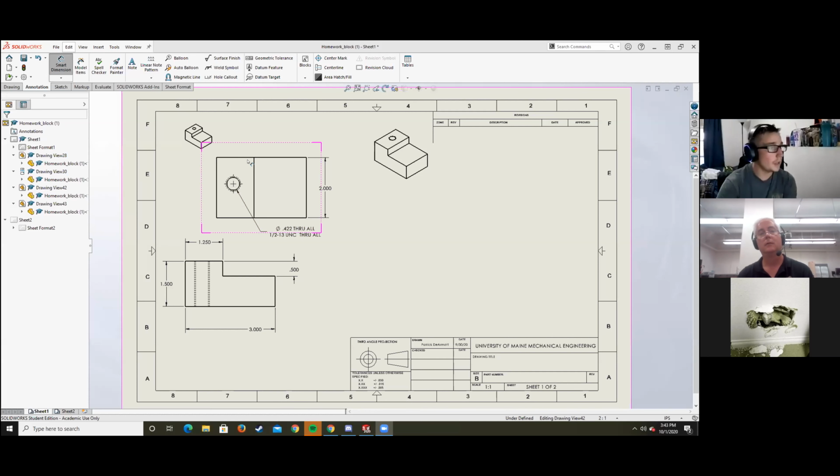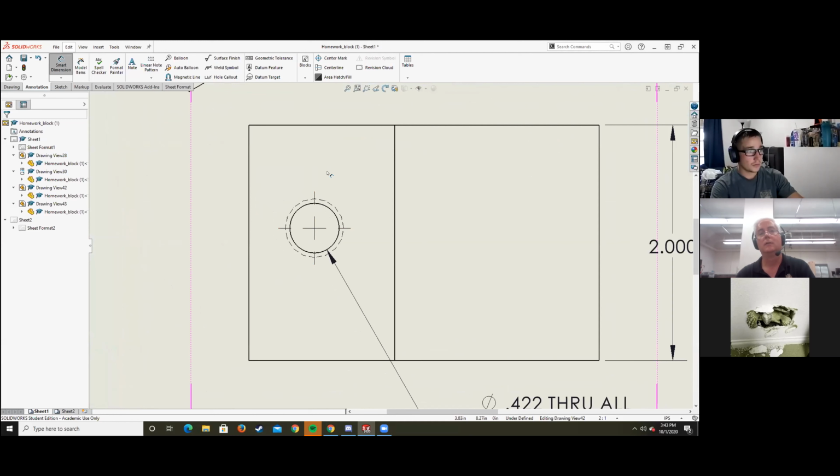All right. So I can go and try to select this, but then it gives me this view right here. And then if I go and try to select this, well, yeah, maybe I wouldn't go there. I never like clicking on the center marks for dimensioning. I always like to go between solid edges. So zoom right in, please. Okay, so go to the top of the block, down to the solid edge of the hole. Oh, okay. There you go. I think that's what my problem was.